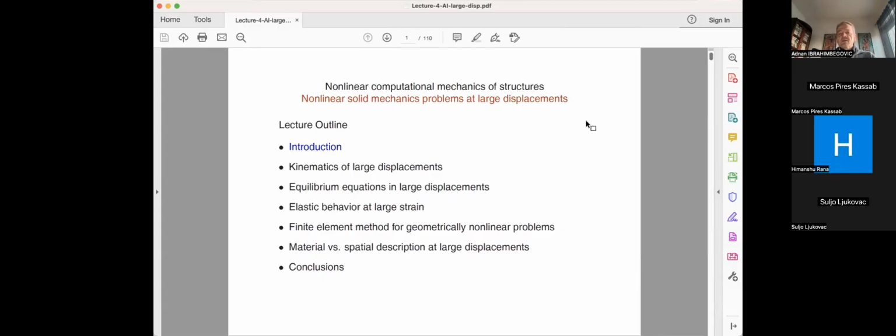Then, given such a diversity of strain measures and stresses, you have to ask yourself, how do I pick the right constitutive model? And then I advocated the constitutive model of Saint-Venant-Kirchhoff, at least that's what people called it, although I'm sure that neither Saint-Venant nor Kirchhoff ever suggested any material of this kind. It says you take Hooke's law connecting the most usual strain measure in many of these books, talking very little about large deformation. This will be Green-Lagrange strain and the corresponding stress, which is second Piola-Kirchhoff.